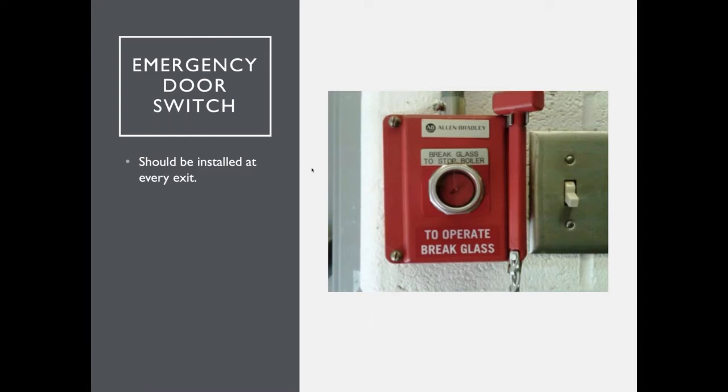Emergency door switch. This is part of the CSD-1, and these are a great idea. I can't stress this enough, because if something happens inside that boiler room, these door switches are supposed to be put at every exit from a boiler room, if your state or local municipality follows CSD-1. And they will save lives and they will save money.